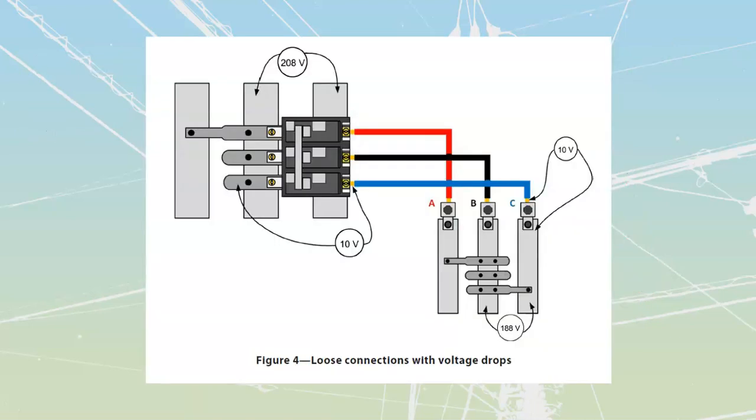Last thing we're going to take a look at, and we have talked about this a number of times, is just torque requirements. Everything has to be done to the torque that is rated by our manufacturer. If it's not done to proper spec torque, it is not a correct rating. Now, I know that most connections in the field happen by feel. You give it a crank, and then you're like, is it a one grunt or a two grunt type of tightness? This is the incorrect way to do it, because we are going to have expansion and contraction as our conductors heat up and loosen.